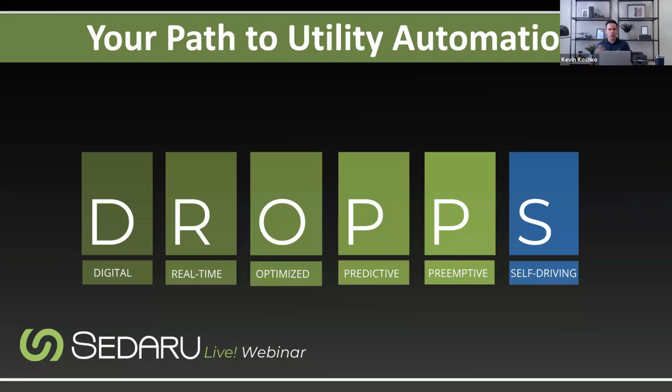No, I think once we walk through it, that's also going to help, because there's so much more we can do with it. A big piece of the predictive side is taking the data we get from the field. After we've exercised all these valves, we have much more meaningful data. We have not only the status and current position, but the actual performance of that valve. How much torque did we apply to it? What do those torque charts and curves look like? And from there, what are we going to do to take action on that?